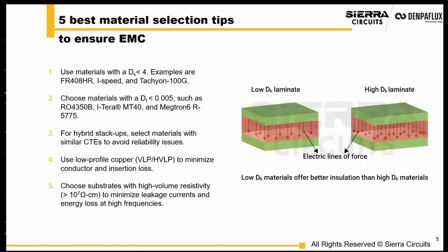So there are trade-offs, not just from electrical properties, but from the manufacturability of the materials. And when we talk about hybrid stack ups, that's really important. Understanding what your via stacks are plays a role in how you build it, and what material you've picked will either make it more challenging or easier for the fabricator. So all very important.